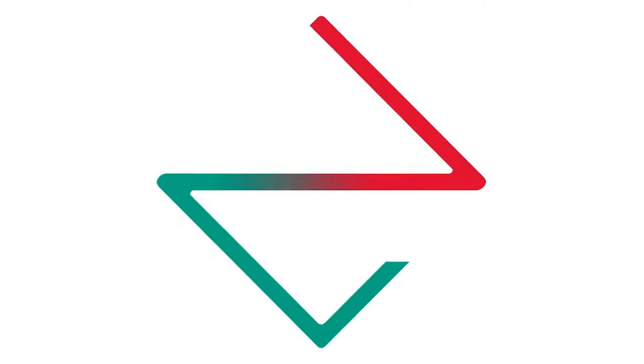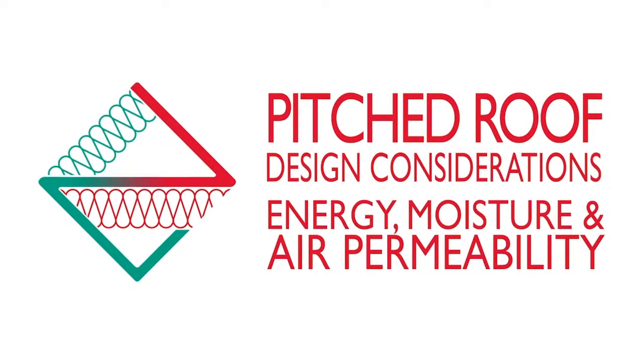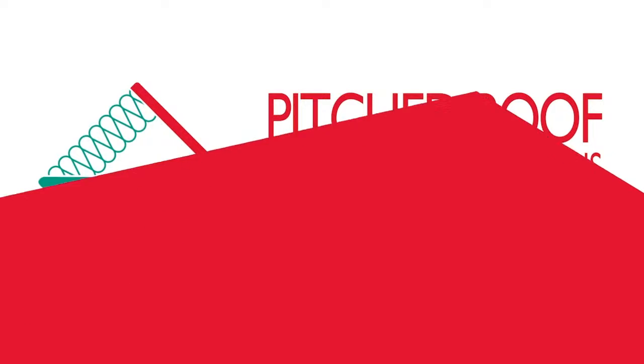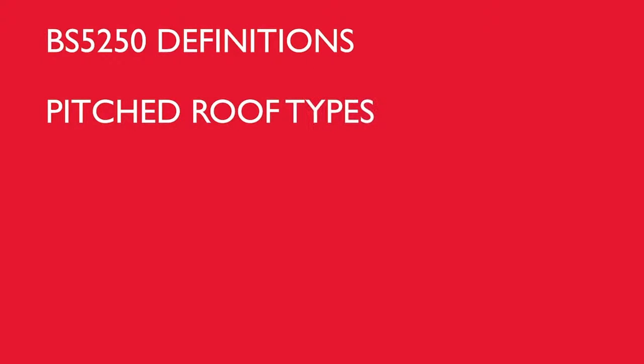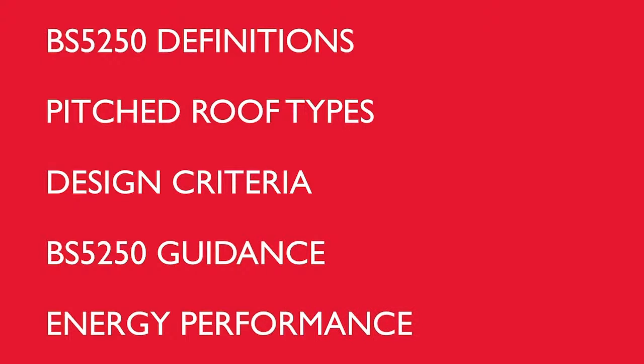Today, we're going to take a look at pitched roofing design and what strategies we can adopt to manage the movement of air and moisture to ensure our roofs are both energy efficient and free from condensation. We'll start out with a look at BS5250, the Code of Practice for Moisture Control, and how it relates to roof design and the building regulations, and some of the roof types it introduces. We'll then look at the physics and design influences in more detail, and how roofing practice is adapting to meet the changing nature of these challenges.